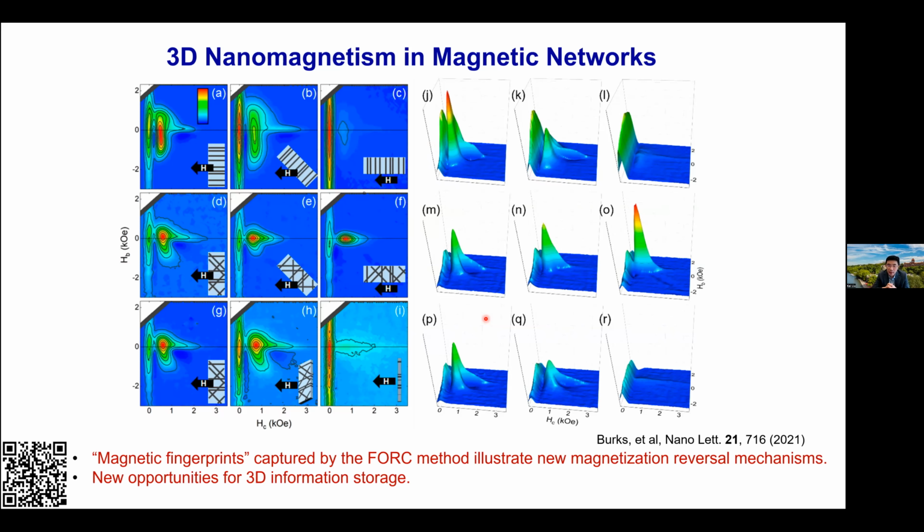And we've recently carried out magnetoresistance studies. We actually observe pinning by the intersections, and that opens up possibilities to use the domain wall motion to implement multi-state memristors.